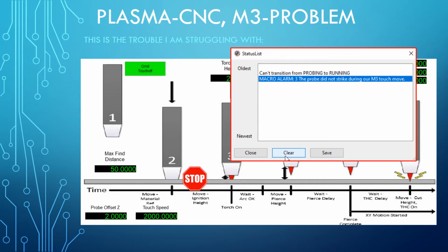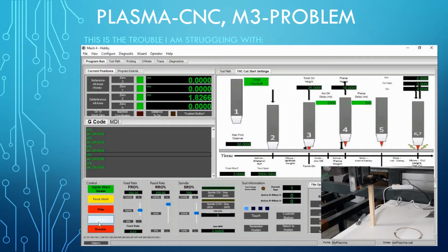The next video shows the problem with the M3 command. The machine is not yet completed, you see. The plasma cutting head is still a wooden stick, you see on the right hand. But nevertheless, the probing process should run completely. For the test, I wrote a short G-code. It starts with an M3 command. If this passes correctly, the Z-axis moves up 30 mm and another M3 command is started. This repeats 5 times. Let's see what happened.